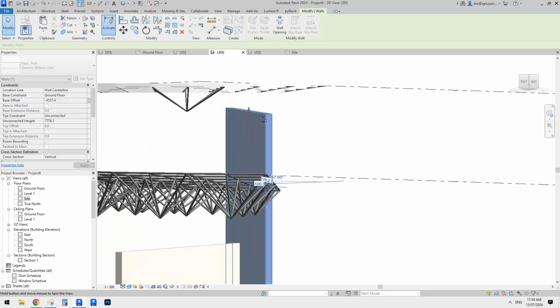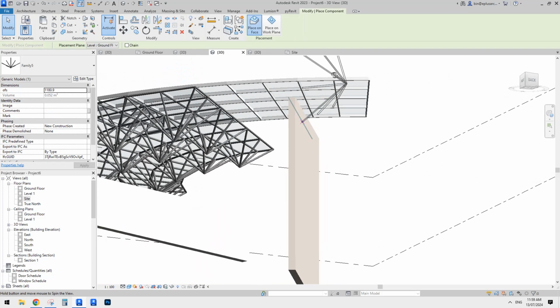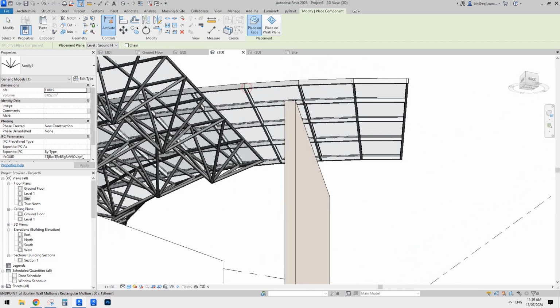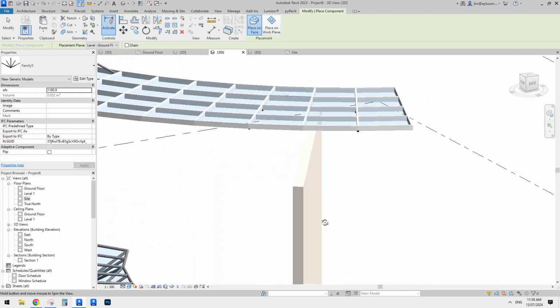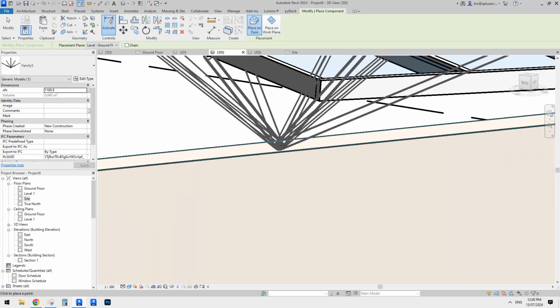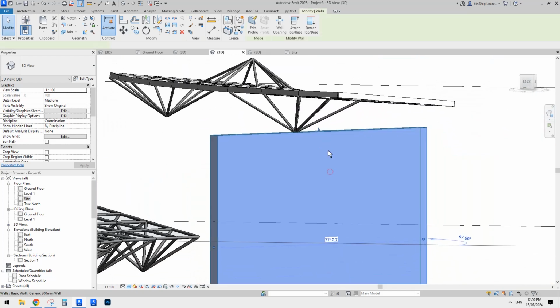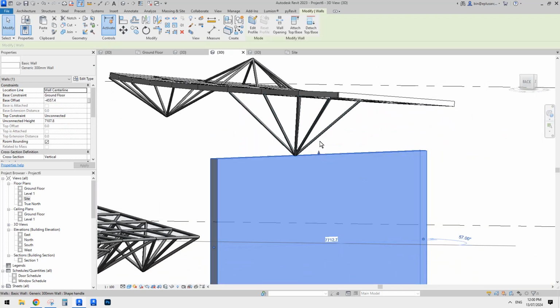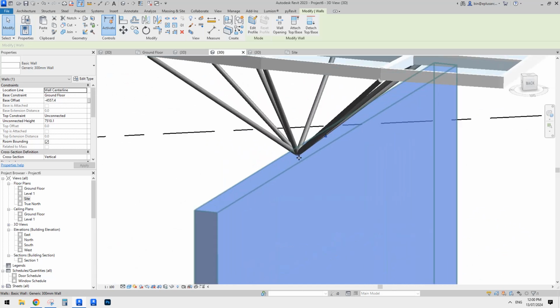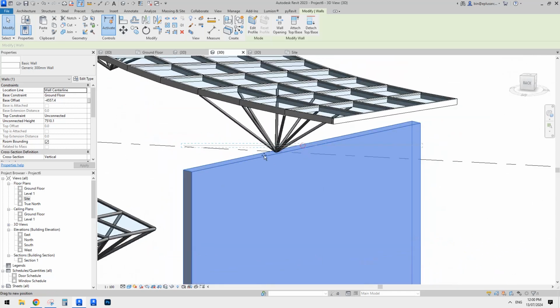So now let's do a couple of these. I'll delete this one. Okay, so I'll CS, create similar. For example, I'll just do one: 1, 2, 3, and 4, and then the fifth point will go on the wall. So I'll just roughly place it here, onto here. Zoom in a little bit. You can place it directly onto the face of the top of the wall, and that's it. And then if you drag the wall down, it will also adjust accordingly, because it's placed on the face of this wall, so it's kind of attached to the wall.